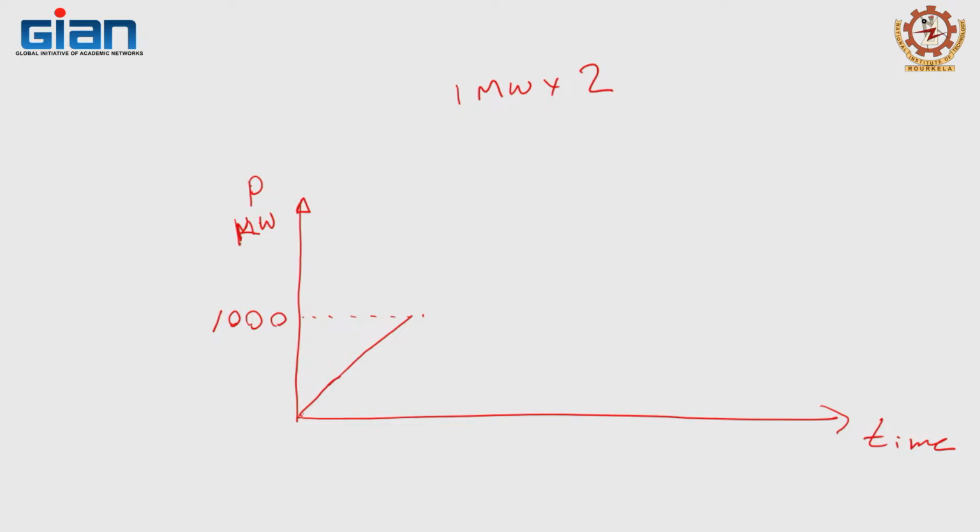Now, how do you do that? You keep this on 1000 kilowatt, the full 1 megawatt, and start the second one from 0? That is not the way, because then the second machine will run on very small flows. What we will do is reduce this a little, to 75%, and then start the second machine.